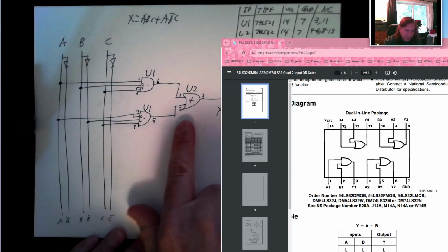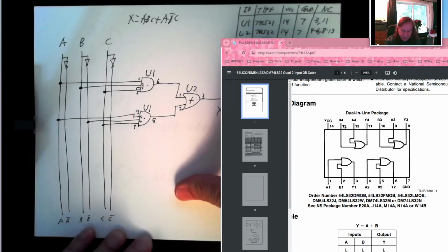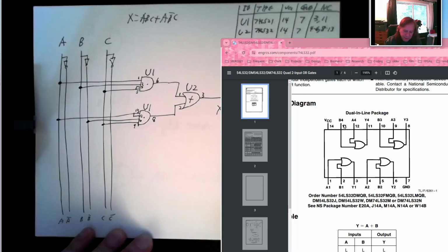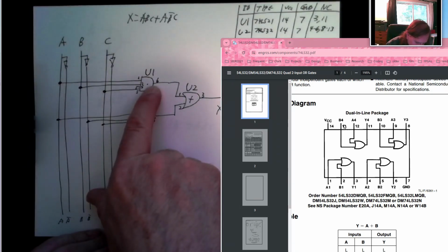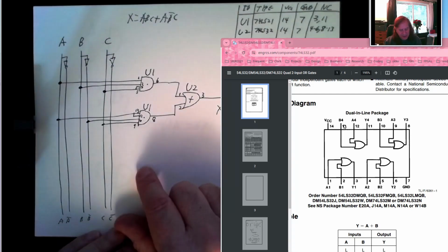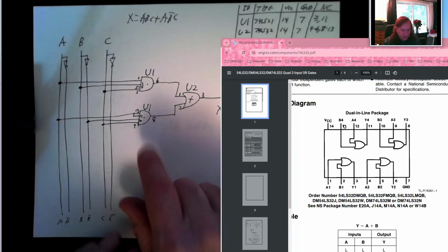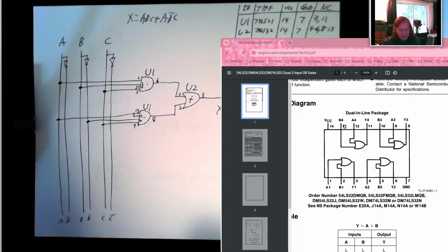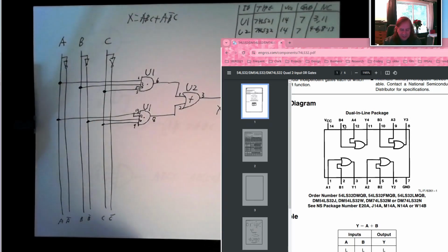So now at this part of the circuit, the engineer says, oh, U2 7432, grabs that chip, puts it in the board, connects power and ground. Oh, pin 1 of this chip goes to pin 6 of that. Pin 2 of this chip goes to pin 8 of that, right? And they don't need to be thinking about truth tables or sums of products or anything like that. Now it's just a recipe. It's just a mechanical process of following what this diagram is telling you to do.